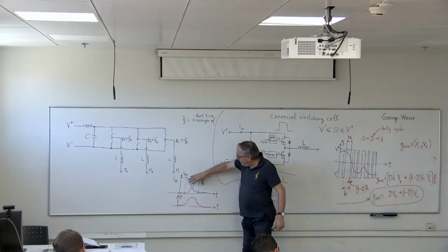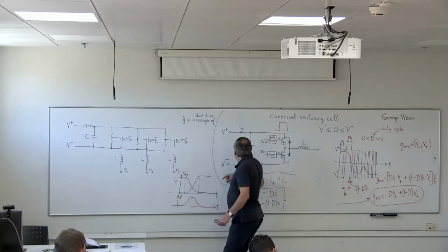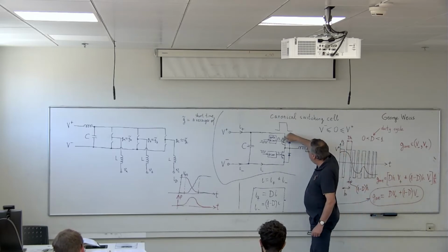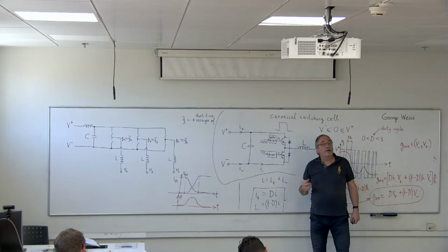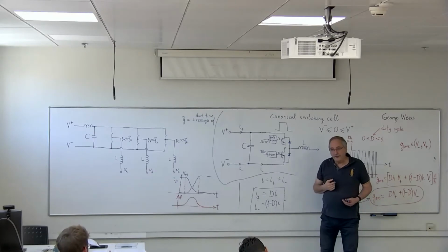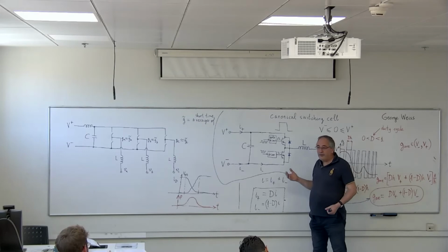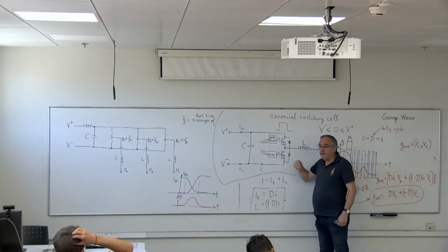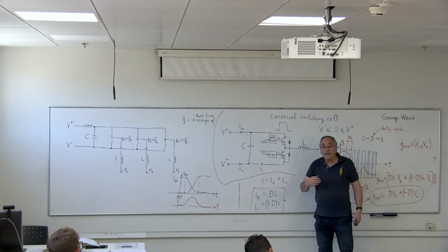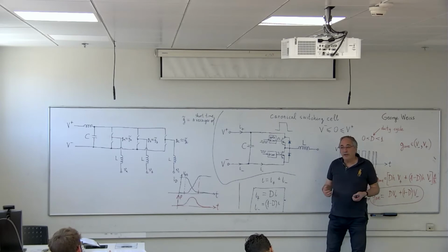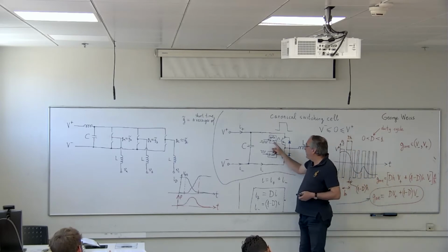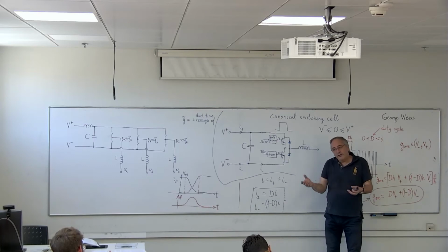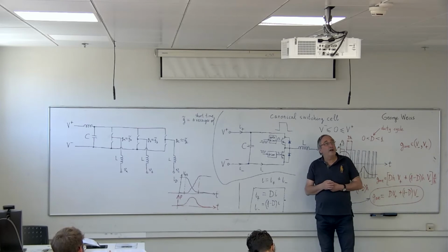So in order to make this switching fast, you need the gate signal to go up and also down very fast. But there is this capacitor here, which means that you have to charge or discharge this gate capacitor very fast. And even though this gate capacitor is not big, it can be of the order of 1 nanofarad. But if you want to charge or discharge 1 nanofarad in a few nanoseconds, that can lead to currents of several amps. So this gate driver must be an amplifier which can provide currents of several amps for a very short time, but it has to be able to provide very high current.